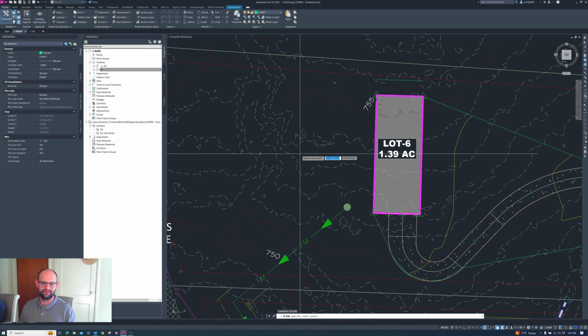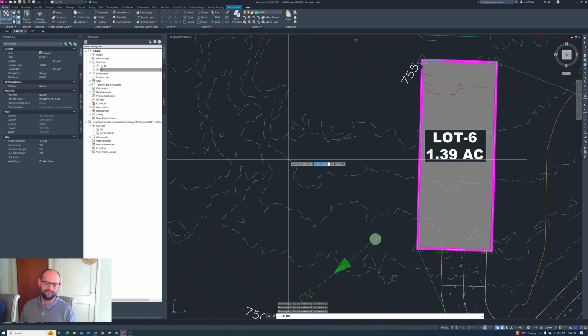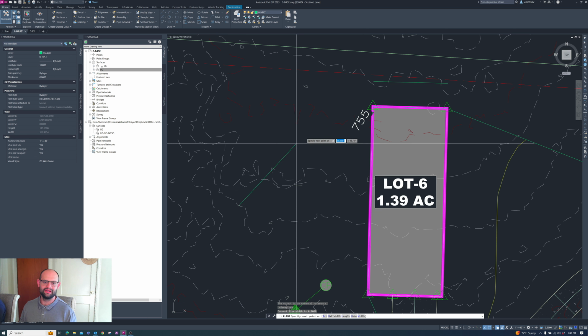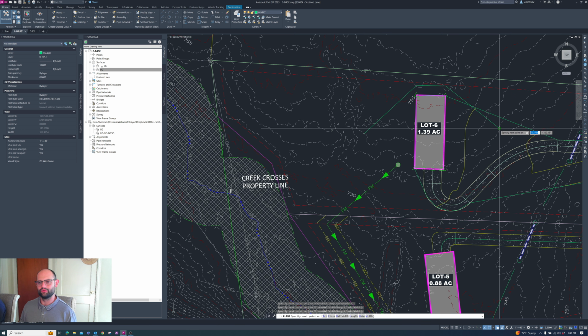And we're gonna add a vertex here to that midpoint. And I think I want that water to drain to right here. So I'm gonna generate a polyline along where I want that flow path to be. From here to here, a high point along that flow path we'll put here. Click that in, work back this way.